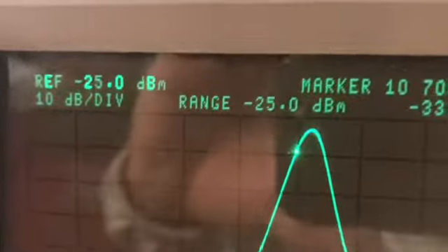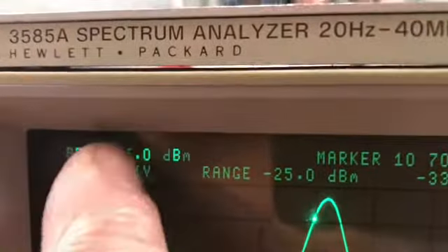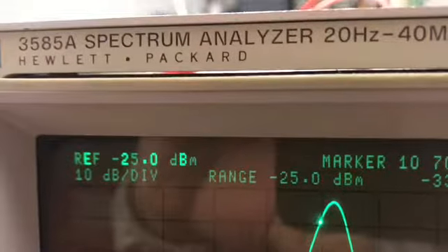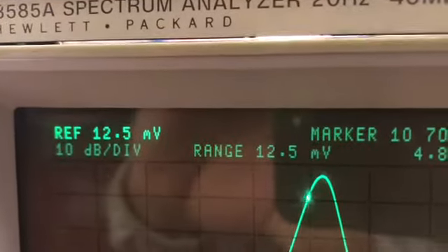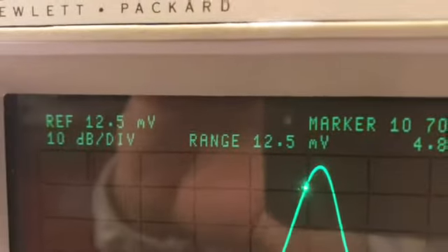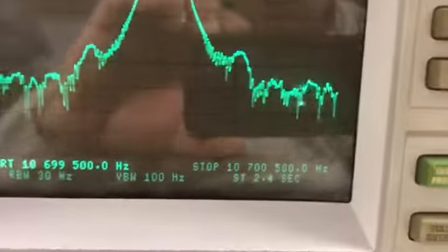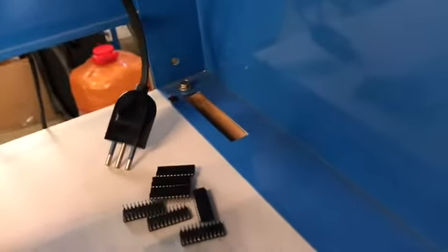If you see, there are some letters here that are highlighted. If I go to complete highlight them and then move to another place, then they go off. So it seems that we still have a RAM that is not working perfectly, and I have swapped, and I found those are not functioning as they should. I mean, they are faulty.